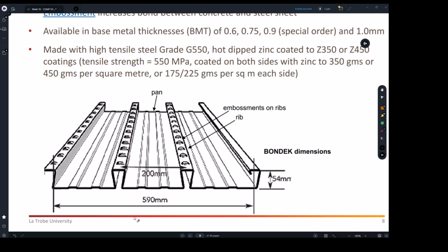So if you go to the steel bar tables, N16s, 16 bar diameter, every 300 millimeters, it is equivalent to about 1,000 millimeters square per meter steel area. And usually this lightweight bonding covers it. Just the basic rule of thumb.